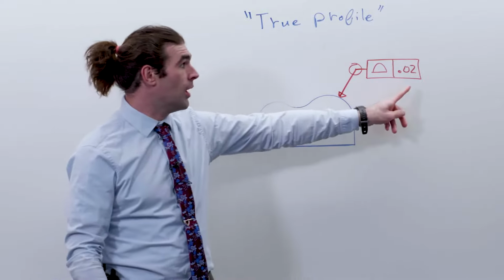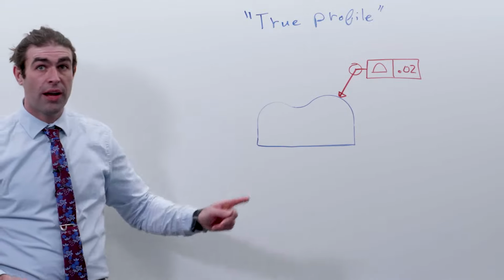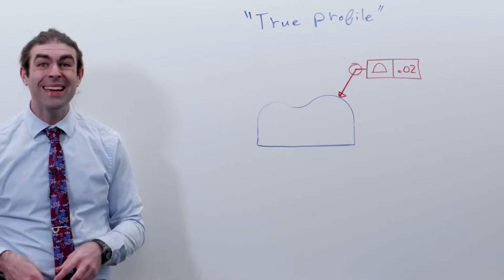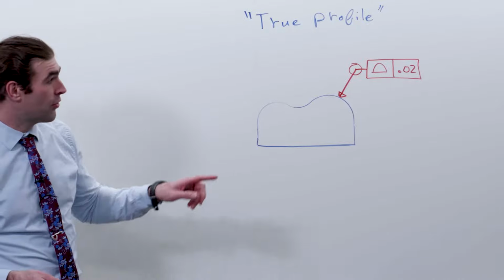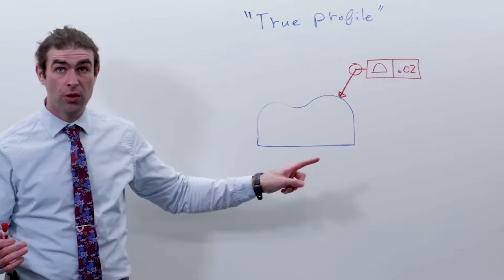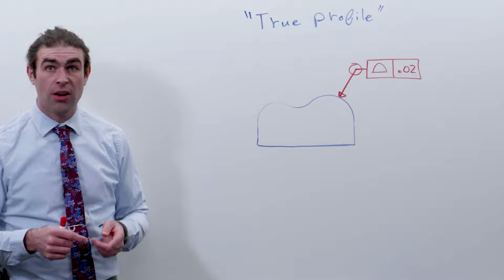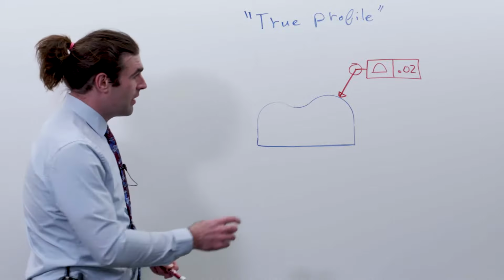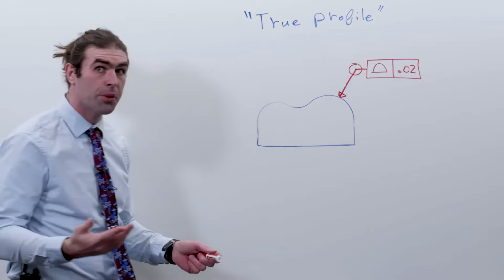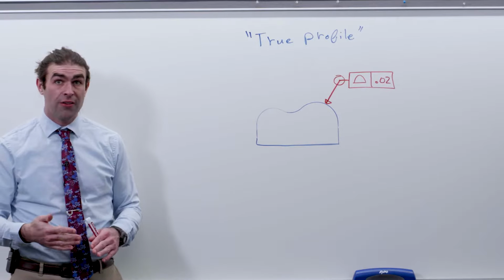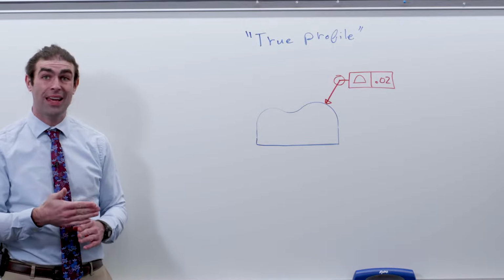And when it's an equal bilateral tolerance, aka the tolerance is split on the true profile, which is the default requirement, you've got half your profile inside and outside of the true profile. What I'm trying to get to is that the true profile is normally just the part outline, so the visible lines on the drawing. And then your tolerance zone just follows the part. So the technical way to define it is that tolerance zone is perpendicular to the true profile at every point.